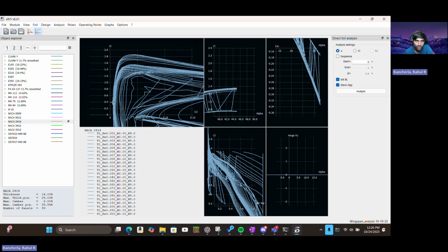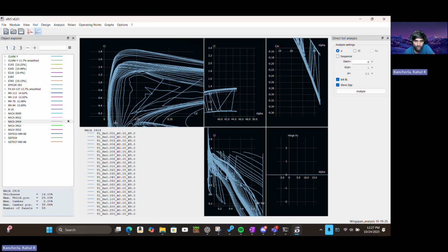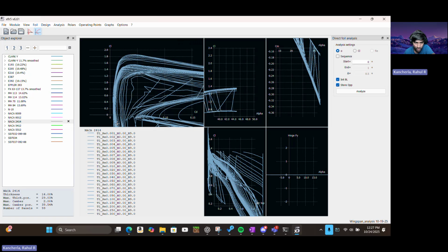At low Reynolds numbers, the coefficient of lift will slowly increase, and then coefficient of drag increases, which is the x. Typically, you want coefficient of lift to go from 0 to around, the highest I've seen is like 3, and then coefficient of drag should stay under 1, really under 1 for an airfoil, especially one that you want to use for a wing. As you can see, the graph doesn't go beyond 0.15.